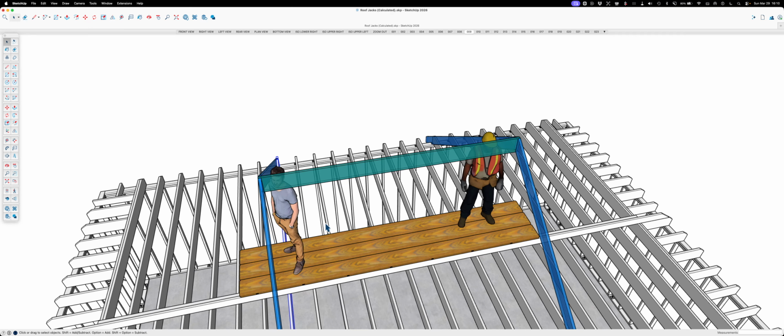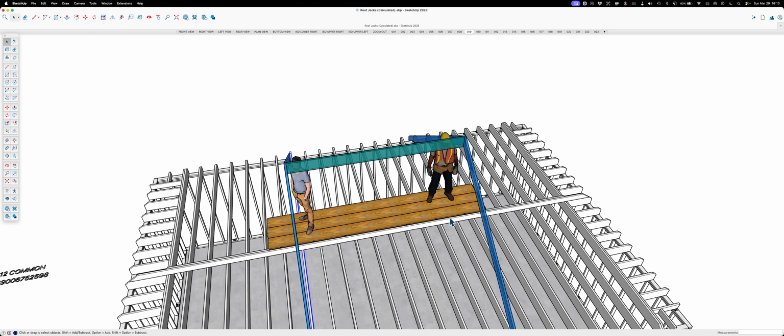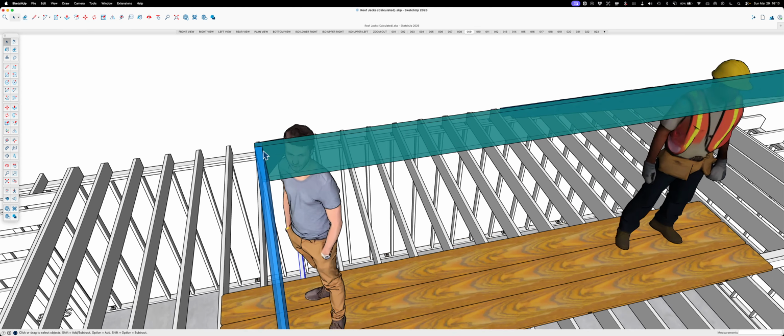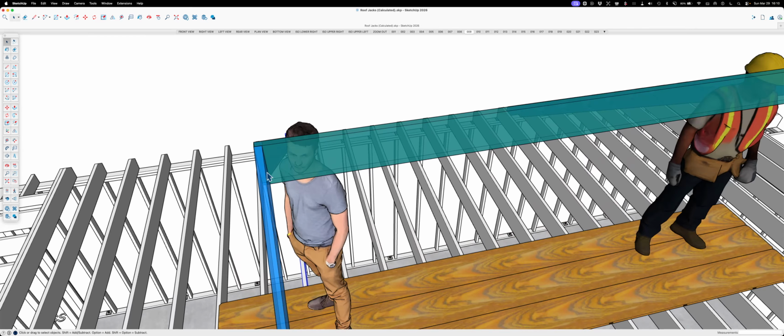And then both parties, once the bottoms are nailed on all four, both parties get up on the scaffold. You raise the ridge, and you kind of put the ridge on your shoulder and lift it up while holding these rafters and scoot it through till it's flush. And then I always shoot from the back side of the ridge into the rafter, like 1, 2, 3, 4, and then come on the other side.